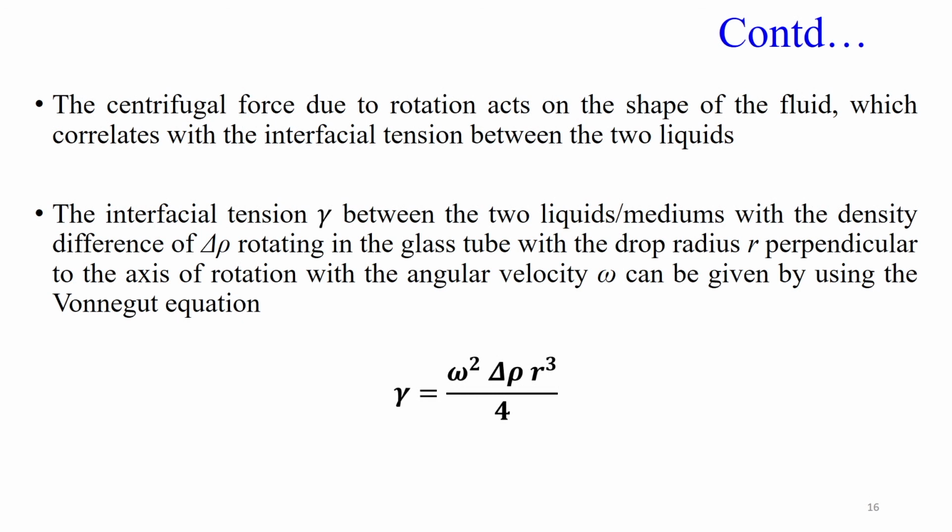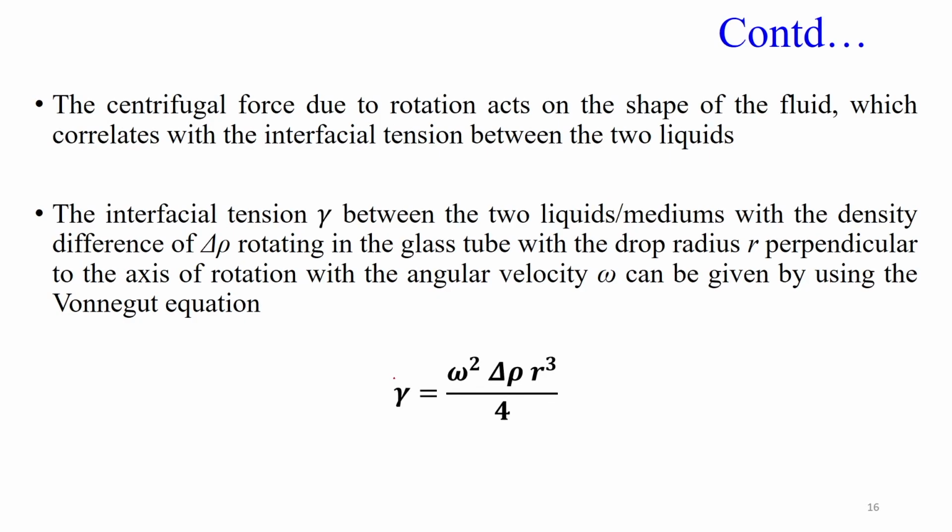As we said, there will be centrifugal force which comes from the rotation, and of course, there will be the interfacial force between the two liquids, and this interfacial tension is related to the speed of rotation, the difference in the density of the two liquids, and r, the drop radius.